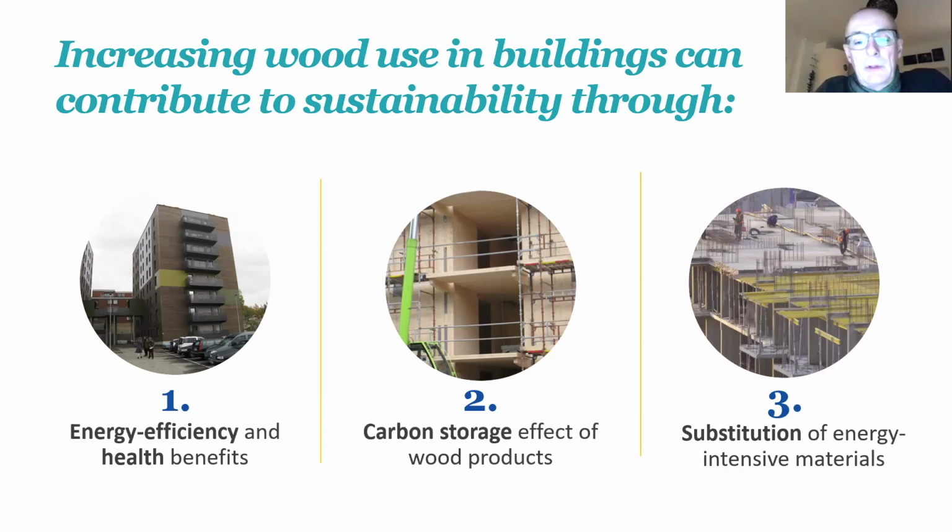The main thing when it comes to the environmental side, of course, is the carbon storage potential, and roughly half of the dry mass of wood is actually carbon. So a kilogram of carbon equates to about 1 2/3 kilograms of carbon dioxide required to synthesize wood. And of course, the other area is that if you're using wood in place of another material like concrete or steel, then you're not using those materials, and in doing so, you're saving the emissions from their production. This can be quite a significant saving as well. So there are many good reasons for utilizing wood.